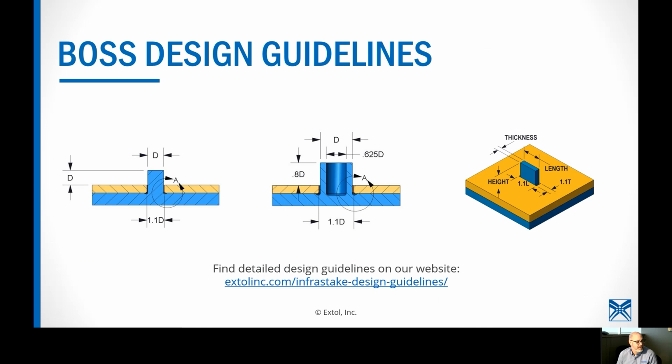So before I move into these guidelines, do you have any other questions? There's one other that just came in, about the banner light curtain. How is it that we were able to clamp the part but not mark the part with the clamping? Great question. We just adjusted the clamping pressure so that it just comes down and just touches off and holds the parts together. This part was obviously very, very small, so it didn't need a lot of clamping force.